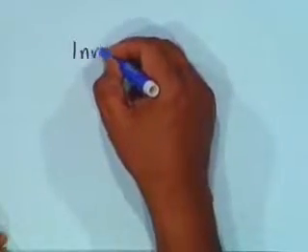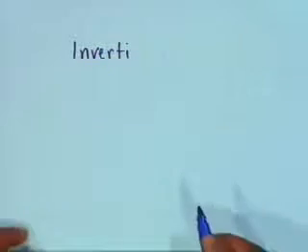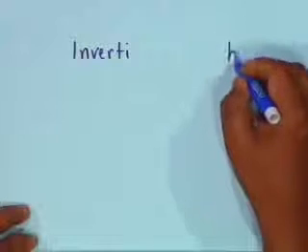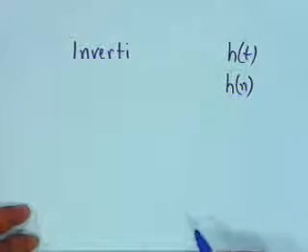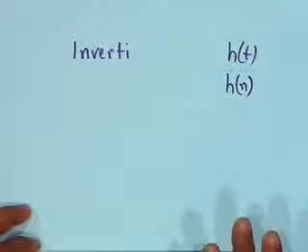Now, under what condition? The purpose of this discussion is to show to you that h of t or h of n, the unit impulse response in the continuous time case or the discrete time case, is adequate for describing the system completely. We have shown linearity, time invariance, we have shown memory or memoryless. Memoryless systems are characterized by its impulse response. Impulse response shall be 0 for every other value of the abscissa except 0 value, the origin. That is, h of n is equal to 0 for n not equal to 0. Similarly, h of t is 0 for t not equal to 0.